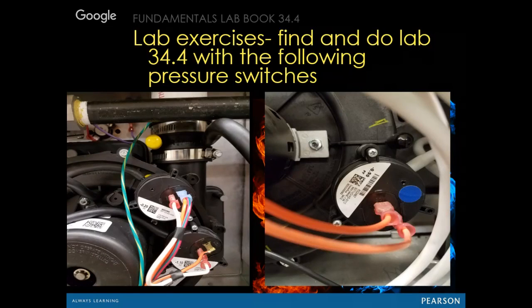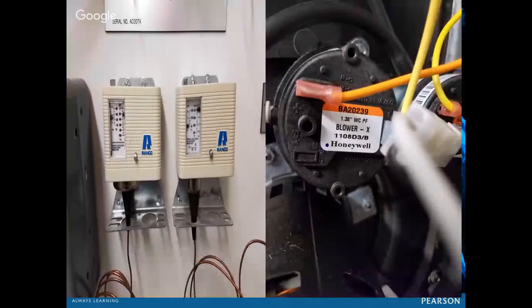You get called to a furnace somewhere and you suspect the pressure switch is gone, man, you've got to jumper that thing out. If your system starts to run and your pressure switch is gone, the reality is you've got to order a new one. You know? So okay. Let me make sure we covered everything that I had in my notes about pressure switches. Okay, pressure switches, what are they? Mention air conditioners, what are they for? Everybody good on those? What they are and what they're for? Me too.